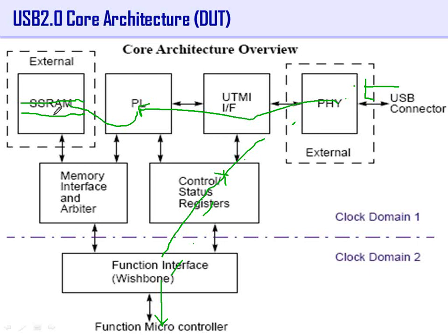Like that, this is divided into 32 regions. Why 32 regions? 16 endpoints. Each endpoint is how many buffers? 2 buffers. So 16 into 2 buffers. And there are registers here. There we clearly tell what is the endpoint 0 buffer 0 start, endpoint 0 buffer 0 size. Then again we say endpoint 0 buffer 1 start, buffer 1 size. Like that, for 32 regions we have size and pointer.